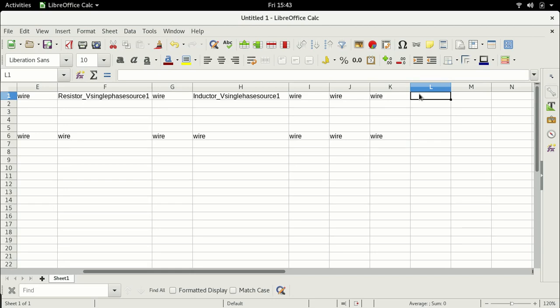So when you're breaking up a circuit into different sheets, you have to connect them together. Now different circuit simulators have different connectors, like in some places there are ports, there are tags, all kinds of things. In this circuit simulator there's only one way to connect two parts of a circuit which are not connected together by wire, and that is by using a jump label. So to use a jump label, I have to say jump. The first 4 letters are jump. This identifies the element as a jump. After that, it's up to you.